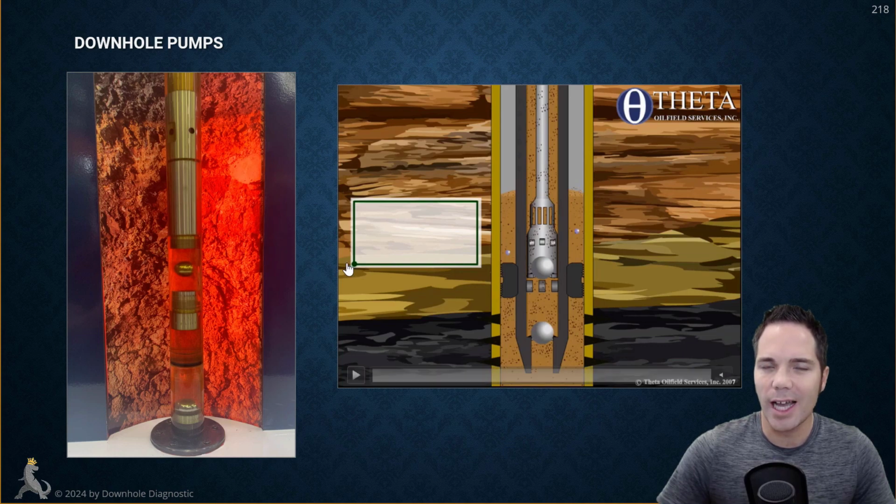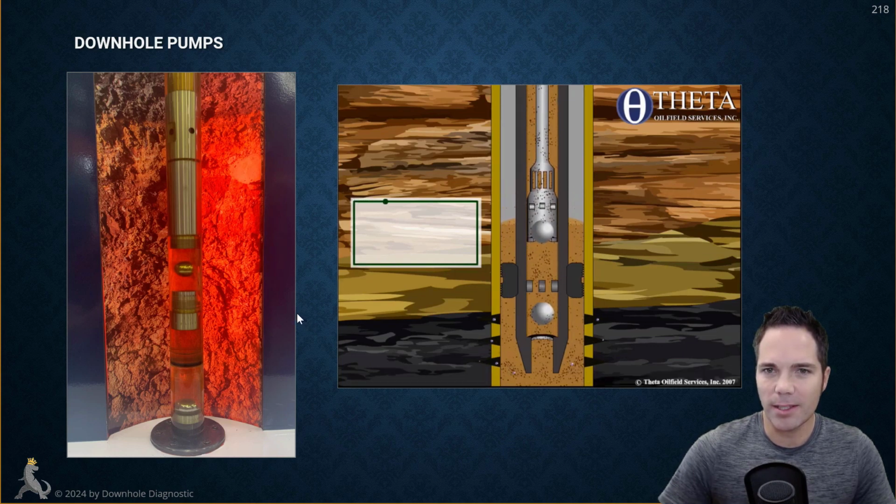It does show us the ideal downhole pump card, and you're going to see as I start this video that it's going to rapidly pick up the fluid load. Remember, this is the load here on the y-axis. It's going to rapidly pick up the fluid load, and then the plunger is moving on the upstroke. This is the position of where it is on the stroke on the x-axis. So notice it rapidly picks it up, the plunger's moving up, and then it's going to release the fluid load right there, and then the plunger moves back down.